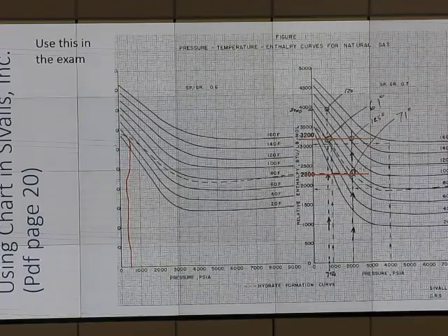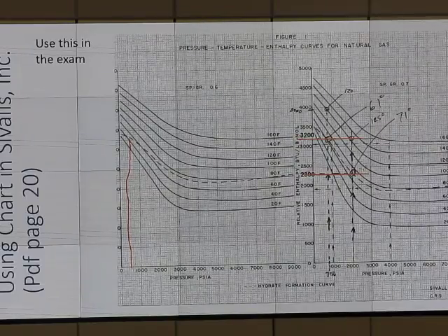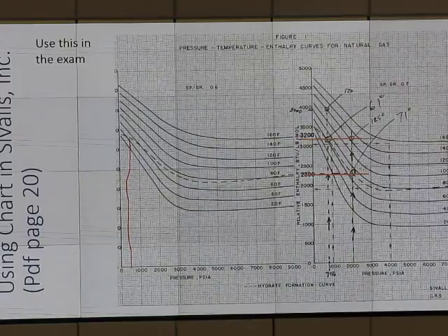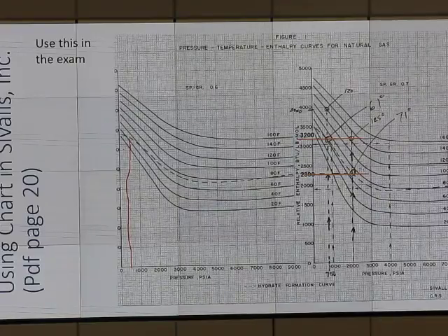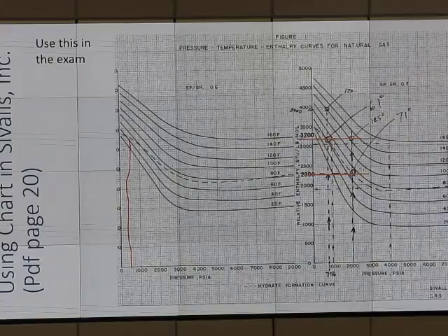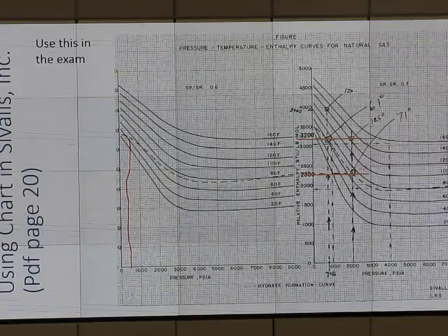When it comes from the well, it is hot, 130, 140 or something. It carries heat from the reservoir. So when it is at the wellhead, you can just choke it there. And it won't form hydrate because liquid, when it goes through a choke, doesn't have JT cooling. And you are at low pressure already. It requires that your ambient temperature is not cold enough to produce hydrate.